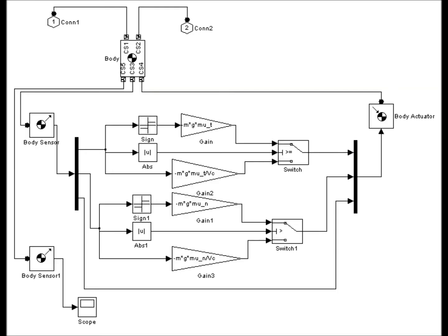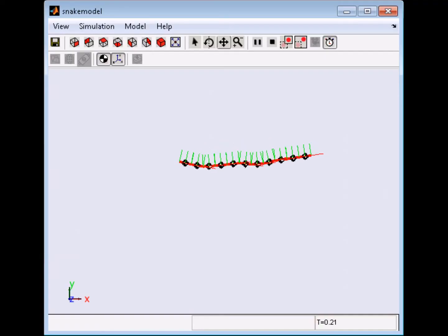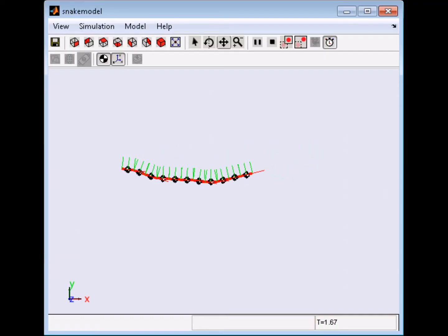We built a block diagram using Simulink and SimMechanics. SimMechanics includes the links, joints, actuators, and sensors to build a snake robot. The friction subsystem uses measured velocity to calculate friction forces. We actuated the joints with the sine function described in the math section.